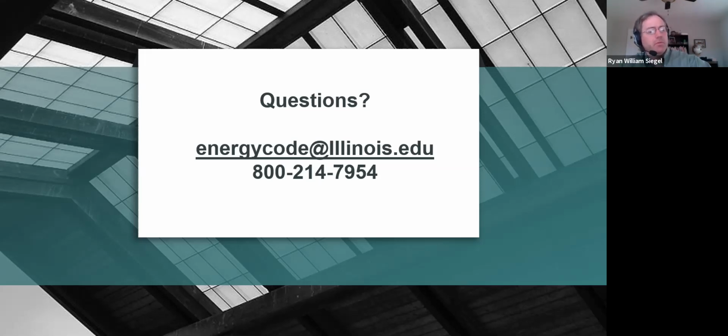Also had another question along those same lines, as also picked up, the IECC does show that you need to have the new building save at least 15% over just a minimum code building, and the reason is under the prescriptive path there is the need for an additional, what do they call it, an additional efficiency package, which allows for flexibility and has 8 different items that you can choose from as far as how you want to go above and beyond minimum performance.